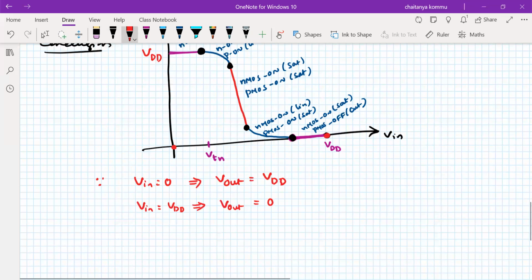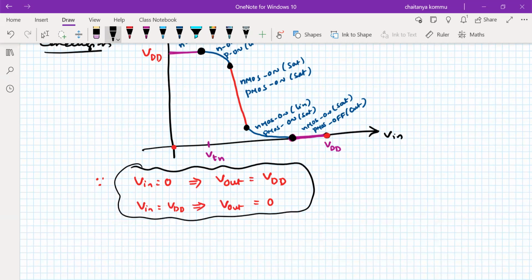So therefore, this is the biggest advantage of using CMOS technology. CMOS technology in the sense that, how many NMOS transistors are there, those many PMOS transistors you should use at the pull-up network. You find that the different inverters, resistive pull-up inverter, depletion pull-up inverter, enhancement pull-up inverter, all these three categories do not produce this kind of approach, because somewhere we found some kind of problem. But in case of CMOS, the VN and Vout, the output voltage values are absolutely the supply voltages.